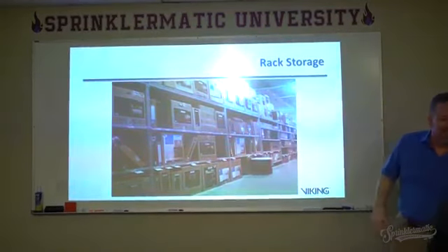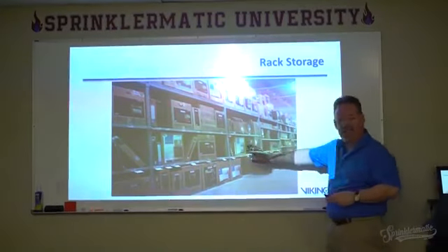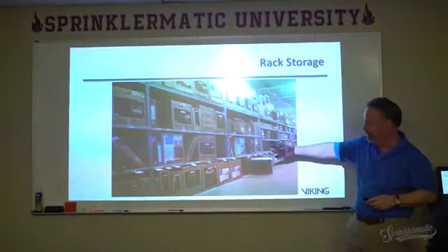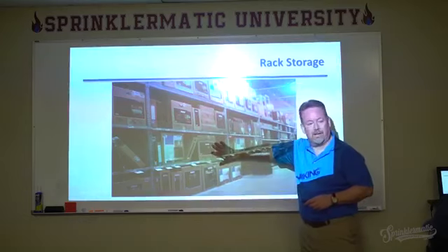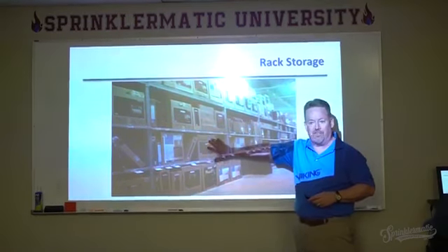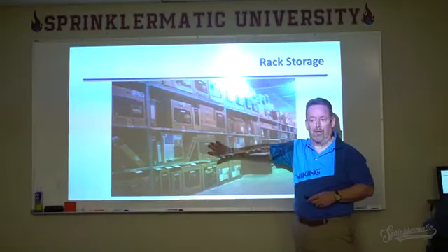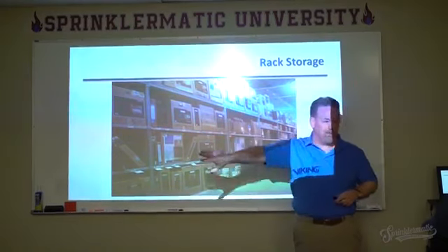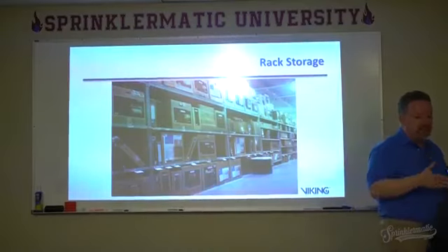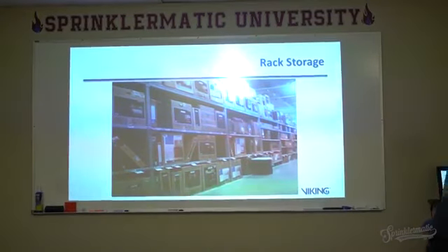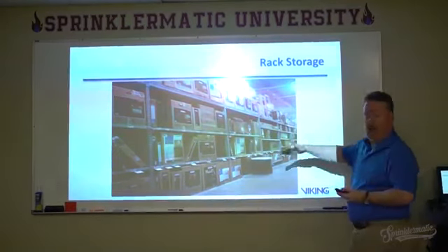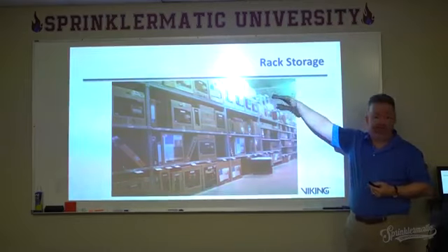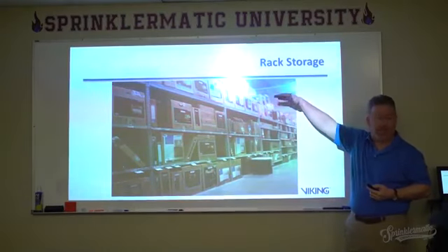This keeps everything right in place while the fire is going. It doesn't go anywhere, it doesn't fall off, it just burns. So rack storage becomes the biggest challenge. Protecting against rack storage is a bigger challenge even than pile storage. We can go much higher, 48 feet high in rack storage.